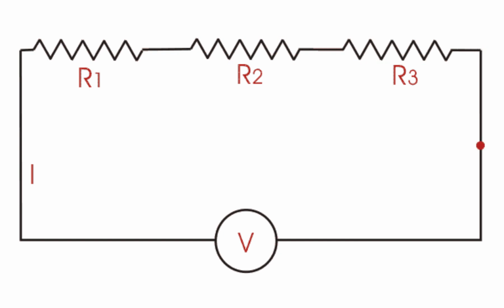A good rule to remember when calculating values of electrical circuits is that the total power used in a circuit is equal to the sum of the power used by all parts of the circuit. That is, the total power can be found in any kind of circuit, series, parallel, or combination of both, by adding the power dissipation of all the parts.